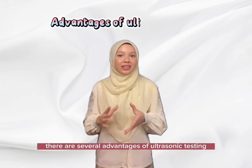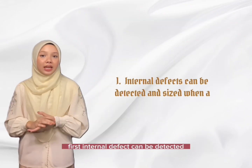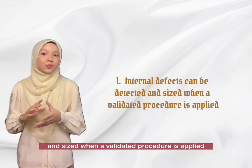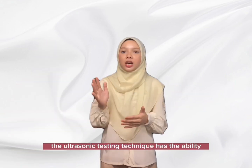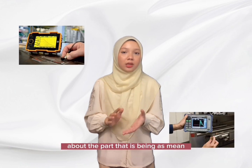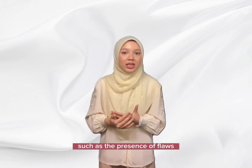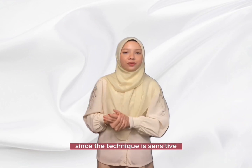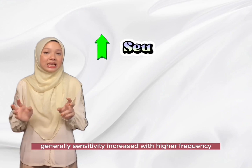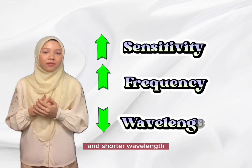There are several advantages of ultrasonic testing. First, internal defects can be detected when a validated procedure is applied. The ultrasonic testing technique has the ability to get information about the part that is being examined, such as the presence of flaws, since the technique is sensitive. Generally, sensitivity increases with higher frequency and shorter wavelength.